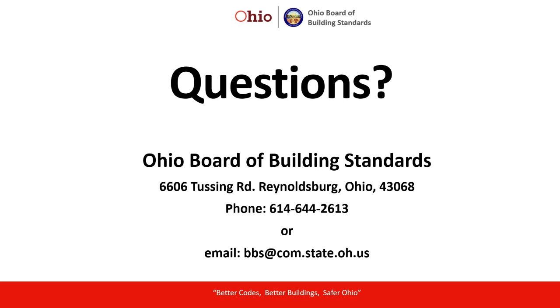Okay, in a tiny home, as a single-family dwelling, accessibility is not required. However, if you want to make certain things accessible in the tiny home, you can certainly make the attempts to do that. I think space limitations are going to be some of your biggest considerations, but there is nothing that requires you to make any dwelling, any building regulated under the Residential Code of Ohio, accessible.